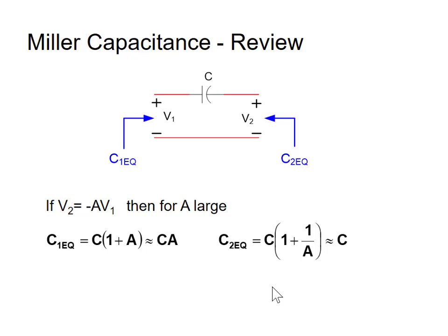By the way, this is called capacitance multiplication. There's a lot of applications where you want a capacitor that's big, but you don't want to go to the resource to put a big capacitor in. So if you build a circuit where you take this voltage here, so here's a node, and you build an amplifier with a gain minus A. If the input impedance is infinite, you feed that back here, and now what you have is a 1 port.